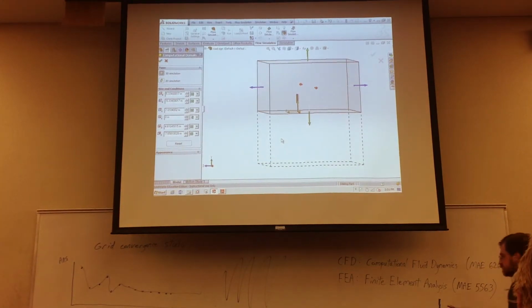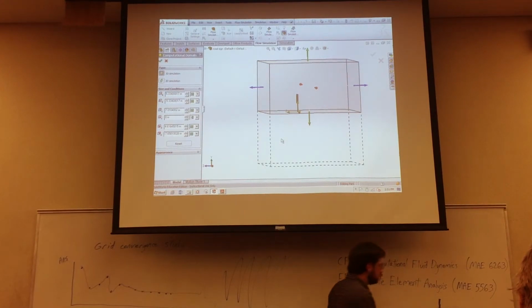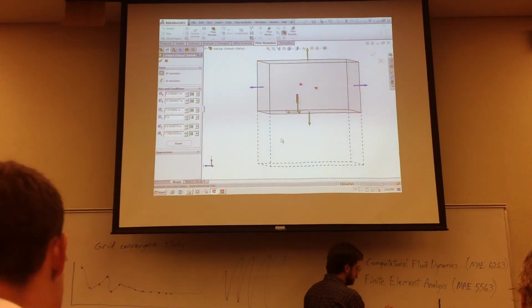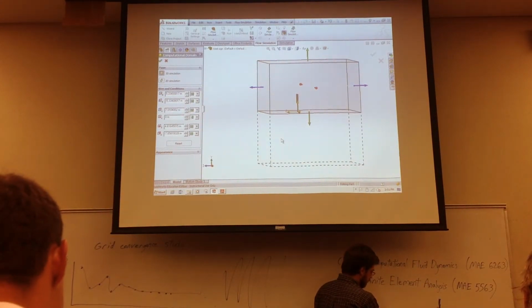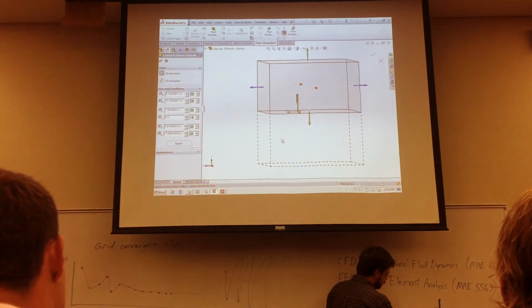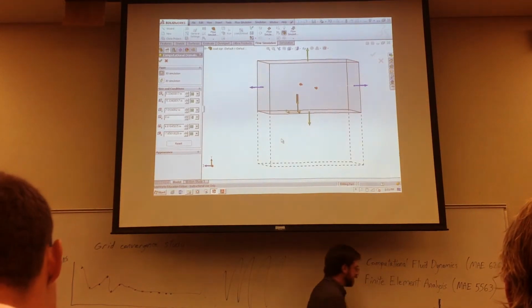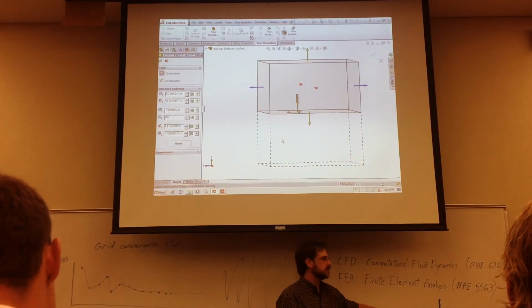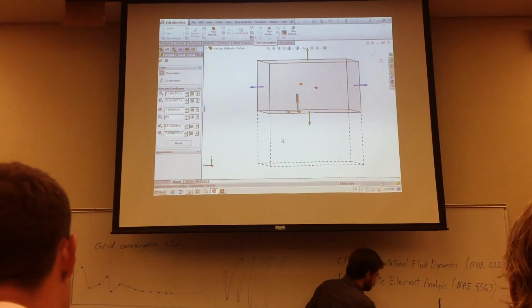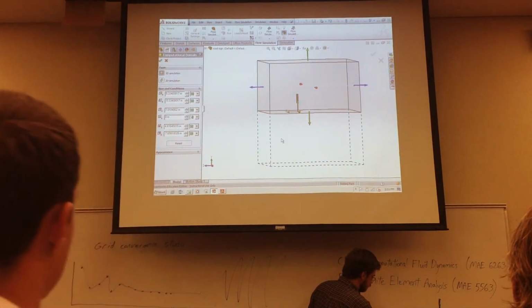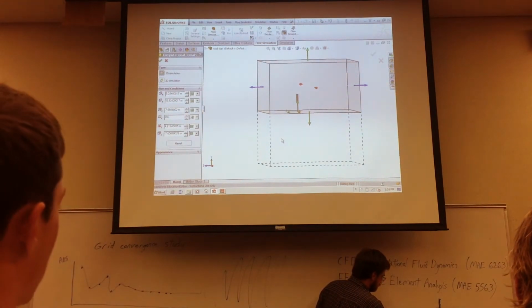And the reason we do it this way is because if you think about what a particle of air is going to do as it comes in here, if it's near the ground, it might come in and kind of scoot down near the ground and travel along, but it can never cross this ground plane. Because on the opposite side, if it's a plane of symmetry, there is another particle of air coming along this way and getting close like that.